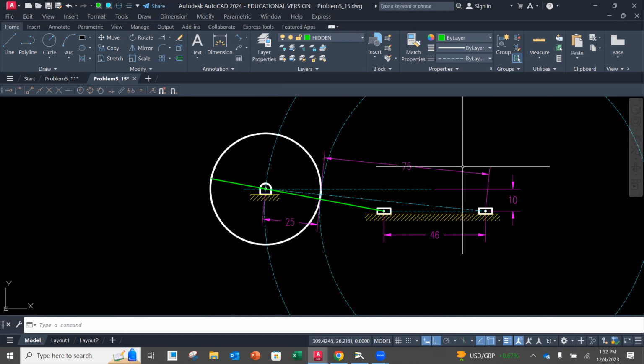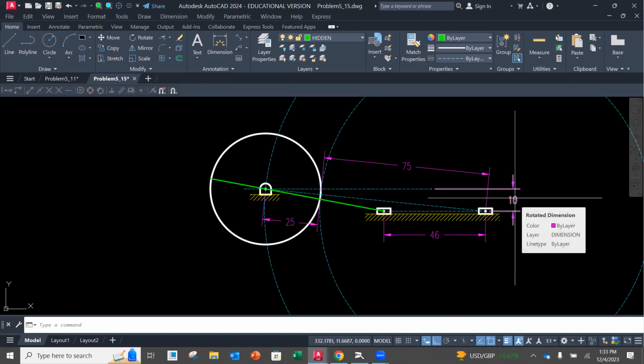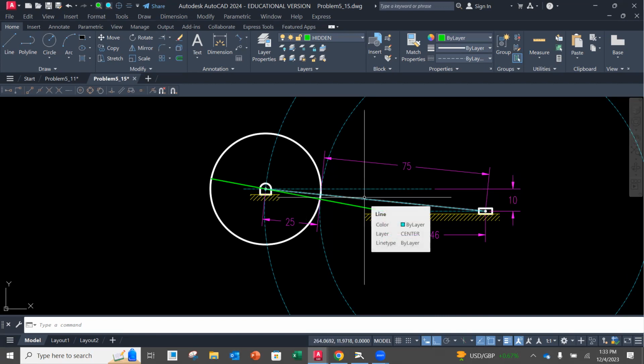And again, starting with your L3 being 3 times whatever you choose your crank to be, that distance has to be less than whatever your stroke is. So that is one approach. Now, the thing about these types of problems is that you're not going to have definitive answers, because everybody is going to come up with potentially a very different offset distance. And that offset distance, or whatever you choose your L2s and your L3s to be, are going to be unique to your design.